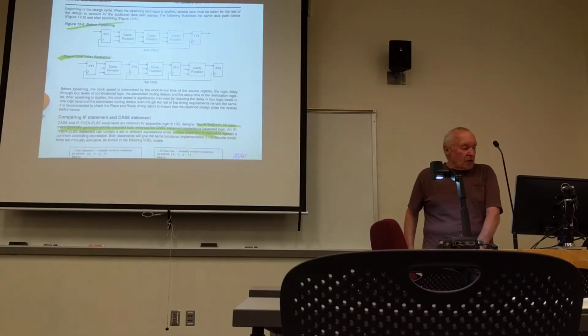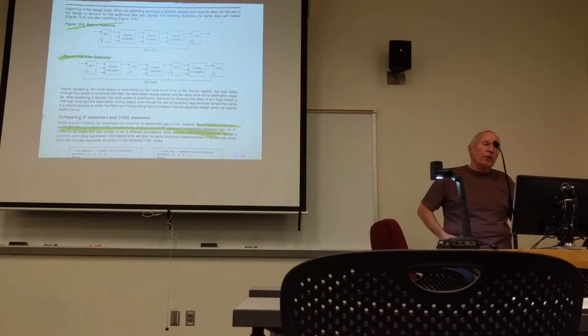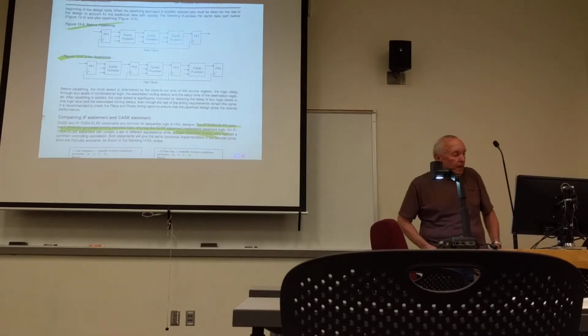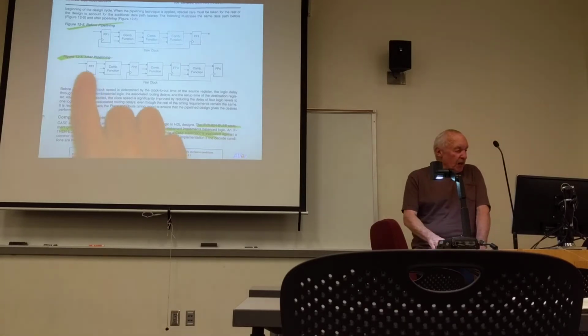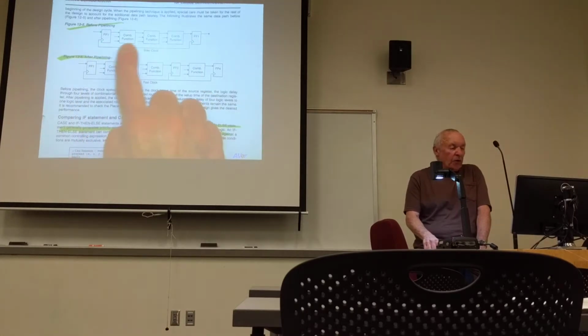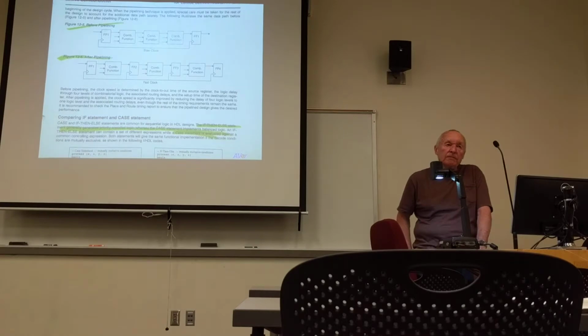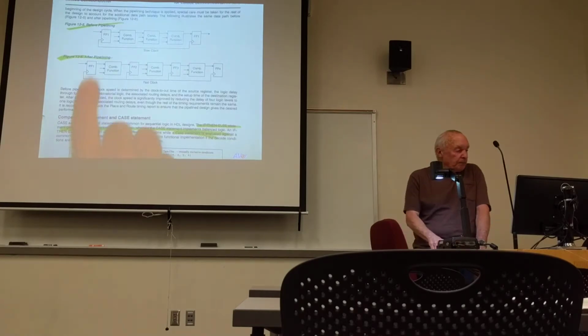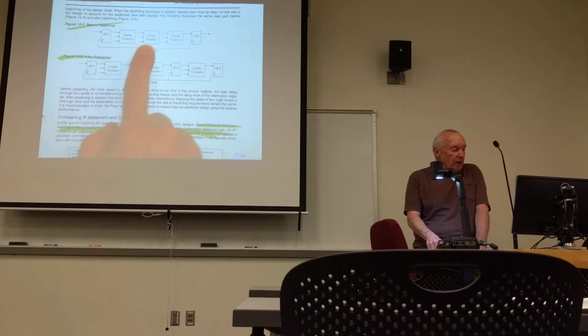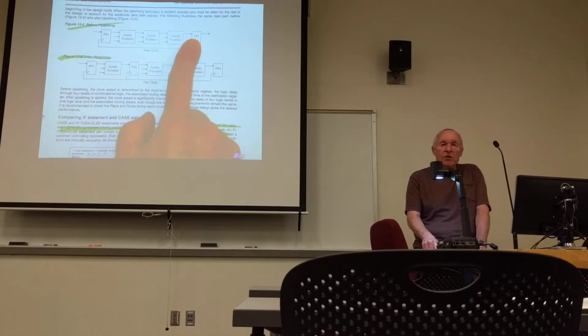This shows the advantage of pipelining, and this is somewhat tied to the idea of registering the output of modules. This shows a particular design, and between this register and this register, there are 3 combinational logic blocks. After you get an output here, you have to go through propagation delay in this block, and this block before you can start the setup time on this register.